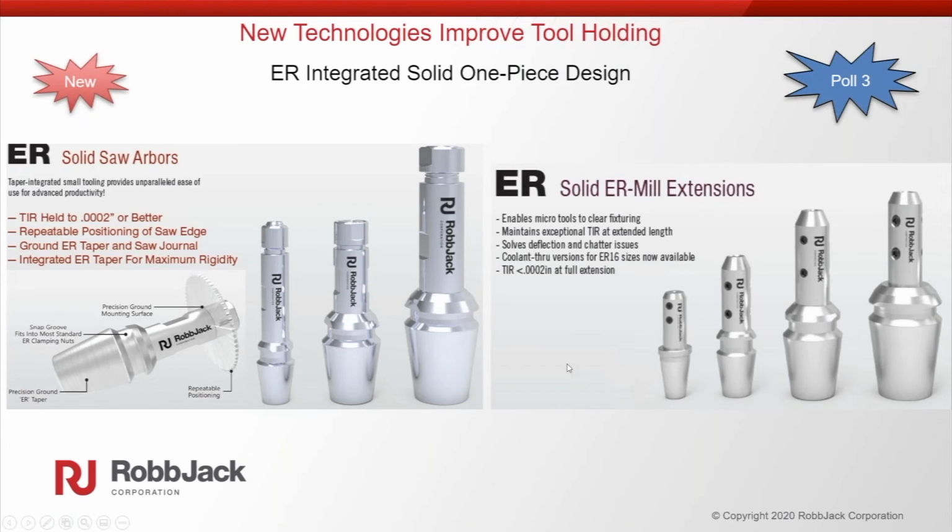Having multiple pieces just adds to the possibilities of having issues and runout. These are a one-piece design, so there are no slots in the collet. The collet isn't expanding and contracting. It's a solid piece, and it really increases the rigidity and the runout.